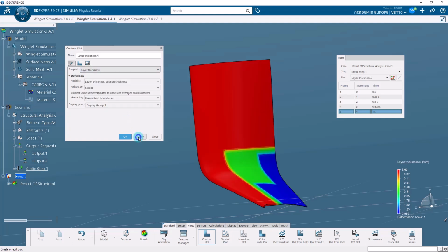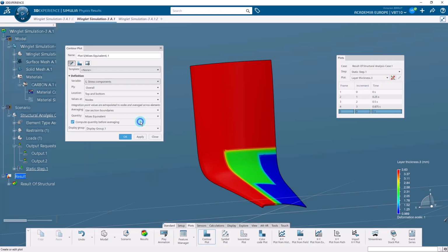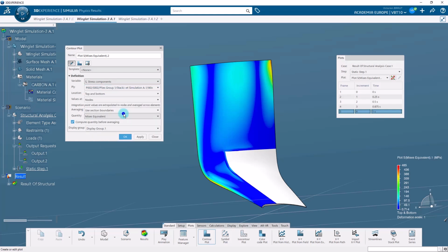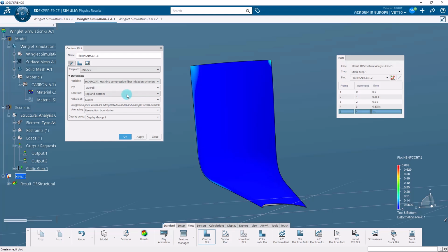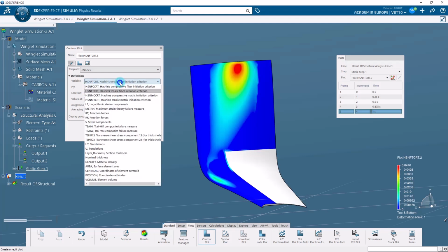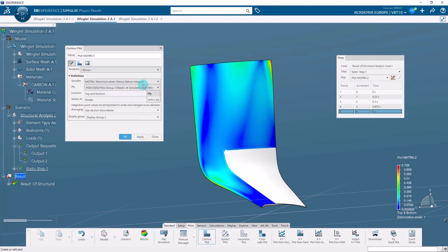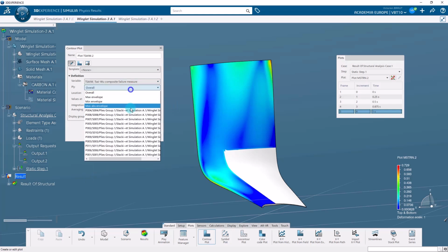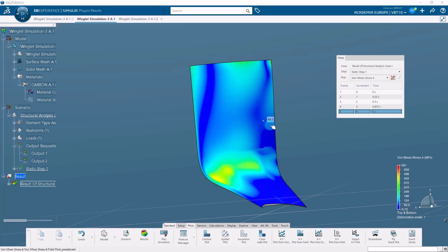You can also create a layer thickness plot to visualize the thickness in all parts. Repeat the same actions ply per ply. Finally, it is interesting to create a ply stack plot.